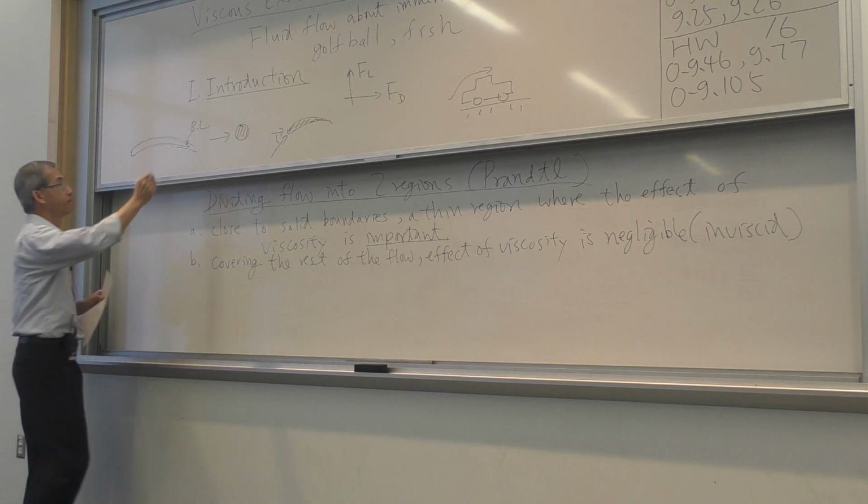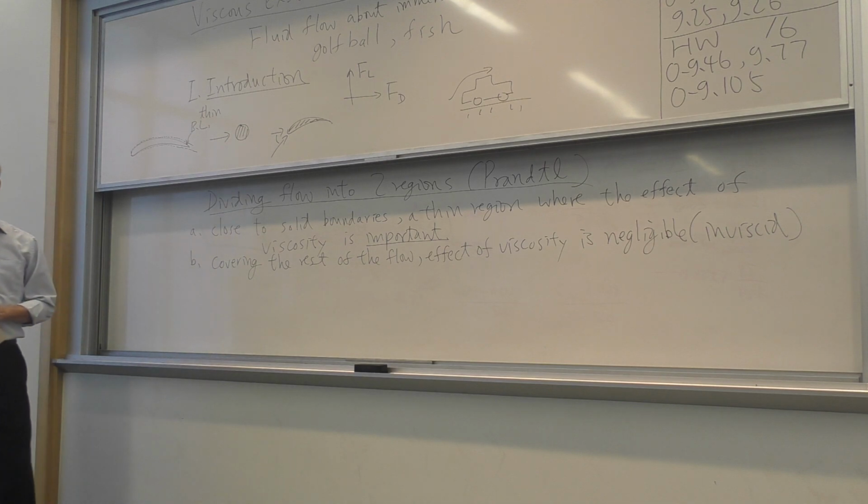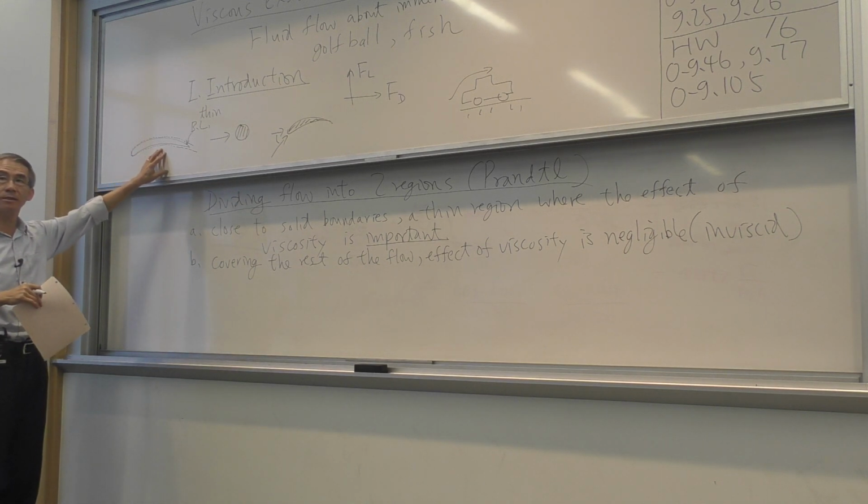And it's very thin. You have homework to allow you to estimate how thick those boundary layers are. Like I said, on a typical airfoil, you're talking about a quarter of an inch, or at most half an inch. So within this dashed line, which is obviously thicker than the geometric airfoil, I have to deal with viscous effect. It's a very complex analysis. I don't think anyone knows what a slide rule is, but back then in the 30s, that's what people used.